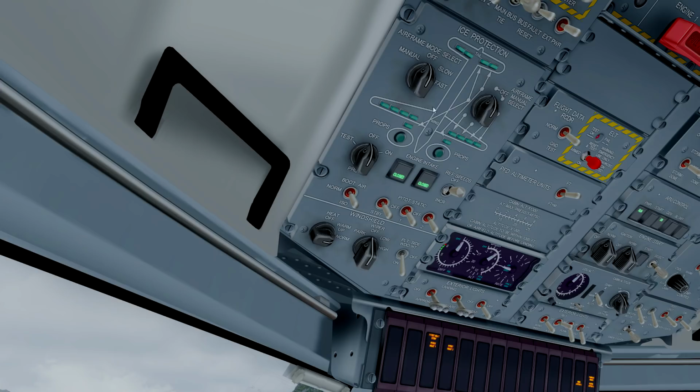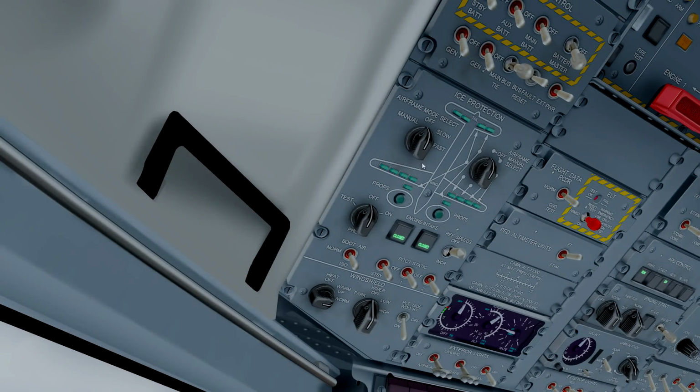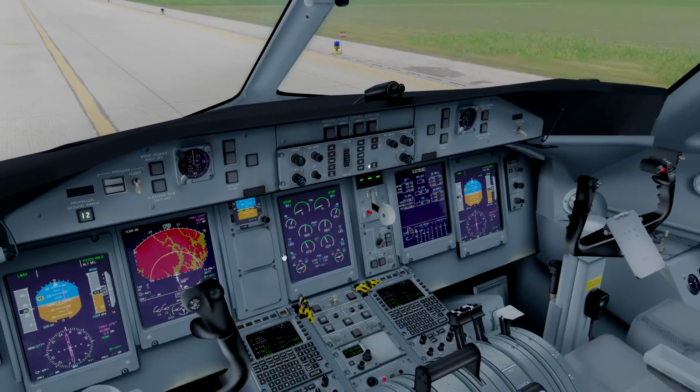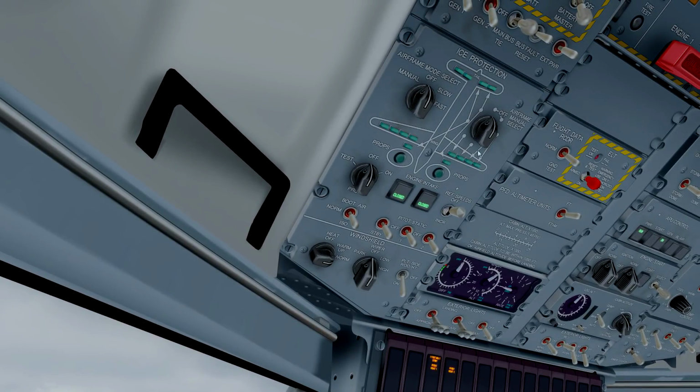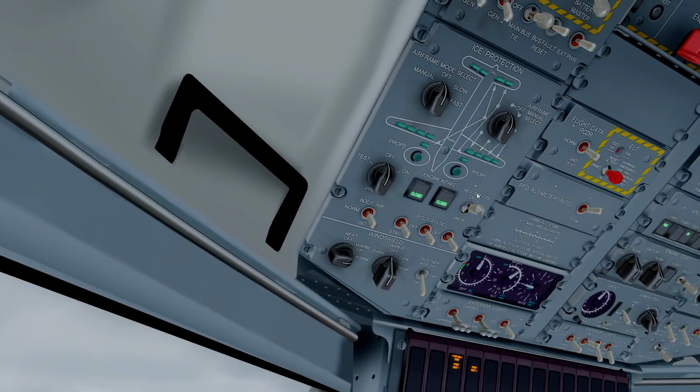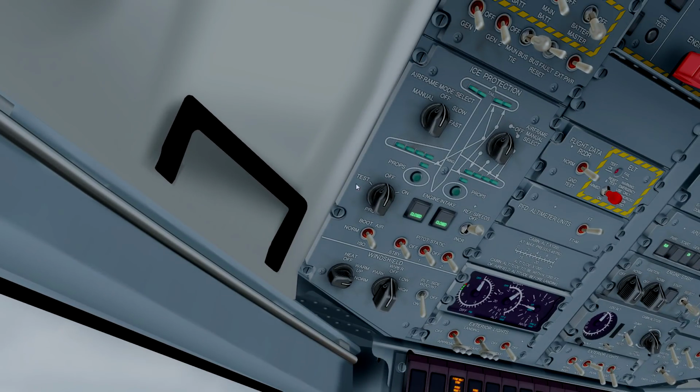The icing system, we don't really have to touch that in this case. These boots that you can see on the outside of the airplane will inflate when you put this system in slow or fast, but that's only really used when you're actually in icing conditions, and these icing conditions will be reported on the airplane, so you don't really have to touch that. Again, the engine intake doors, you have to open that for engine startup when necessary. Same for the prop heat, only when you're actually in ice conditions.